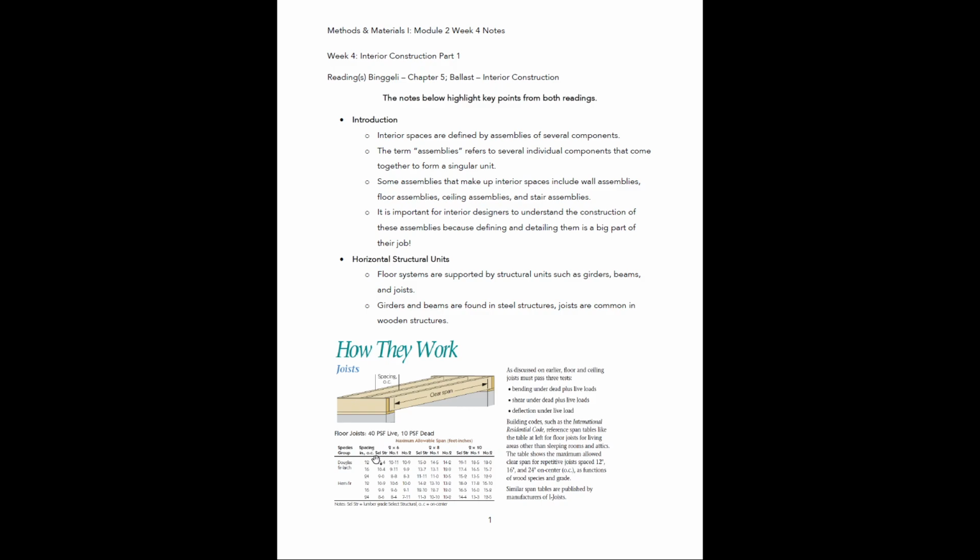So you can see here, this column is for 2x6 joists, and then here's 2x8 joists, and then 2x10 joists, and then also the material that they're made out of. But typically, the spacing is one of these three values here, so 12 inches, 16 inches, and 24 inches. And the measurement for this is taken from the center point of each joist.